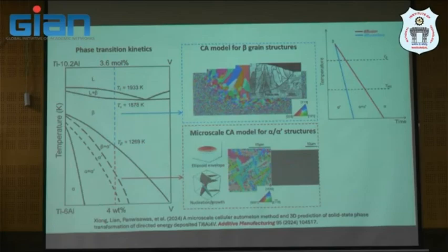So you will see that, if you're interested in this, if you do some kind of diffusion-driven problem and it's followed as normal, it will be like this in forging of titanium 6-4. But if it's rapidly cooled, the phase which is formed will be alpha plus alpha prime. So it is so complicated now, because the martensite here is so important. How can we understand how it's formed, and how can we avoid that?